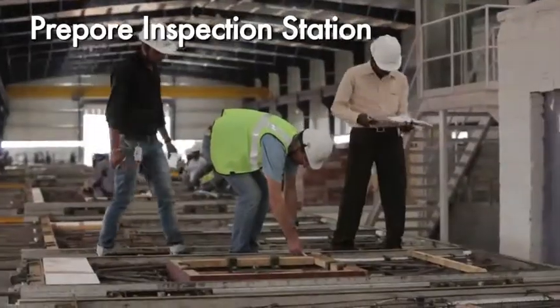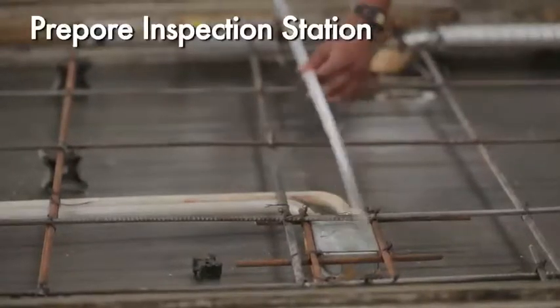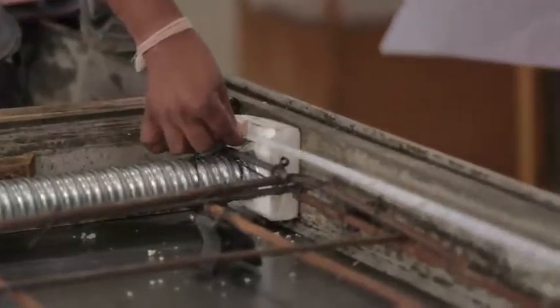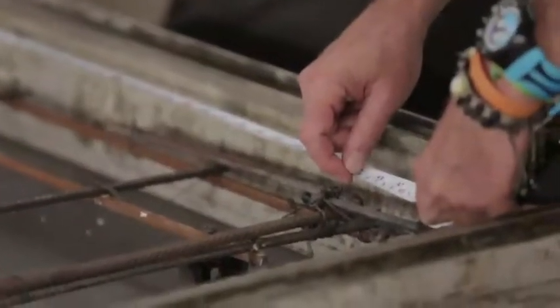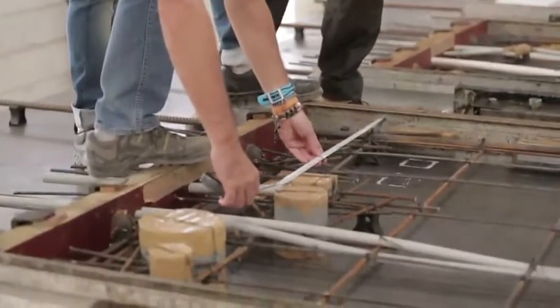Pre-pour inspection station. In the pre-pour inspections, the following checks are required as per shop drawing: opening dimensions, positioning of inserts, positioning of reinforcement rebar, cleaning and cover for the rebar. The pallets are then shifted to the concreting station.